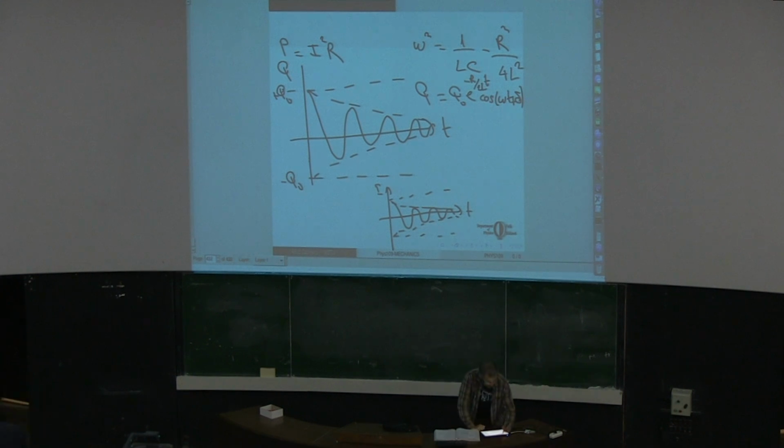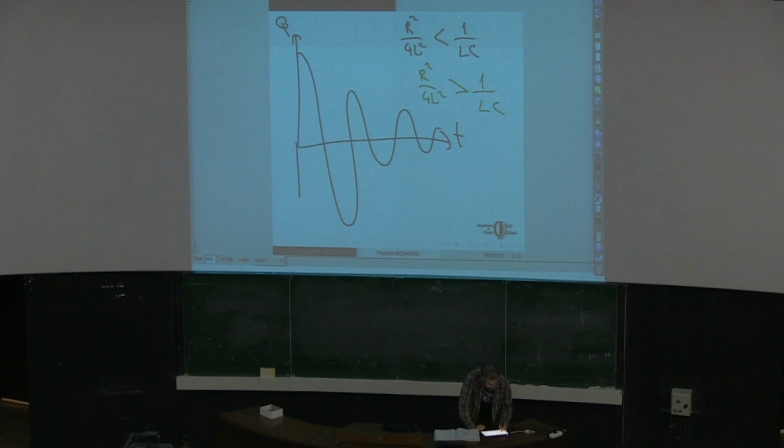The solution we have in this case is not an oscillation, but an exponentially damped system. Mainly we have a large resistor and, let's say, a large L or C. So there won't be any oscillation. The system just loses all its energy before completing one full oscillation. The earlier case is underdamped. This is overdamped.